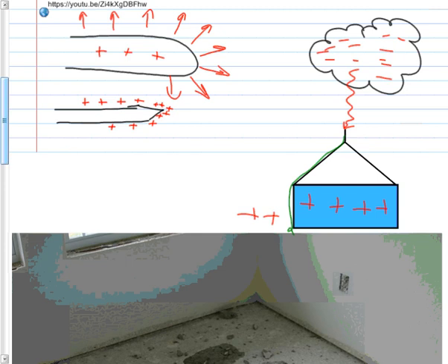And when we do a demo, I'm going to do a little demo with a little miniature lightning rod. And you'll see how amazingly it affects, in fact, it will eliminate the ability of my Van de Graaff generators to strike. We're going to have lightning strikes. They're not really lightning, they're static electricity strikes, but that's what lightning is, just much bigger, going between those two globes. And when I put my little lightning rod on it, it will quit, even though that lightning rod is actually closer to the globe than the other one was. It will bleed off enough charges that it will reduce the charge difference and it will prevent it from striking. So a lightning rod has two purposes.